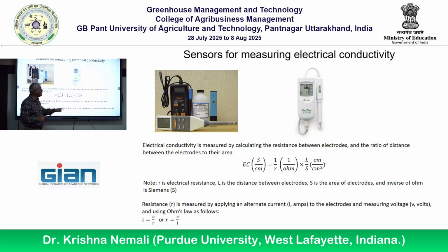You don't want to leave the EC probe open. It is going to affect its calibration, it's going to affect its life, and most importantly, you may end up breaking that bulb. Okay, so always cover it with the cap that comes with it, but you have to add a little bit of water. Keep it moist always.